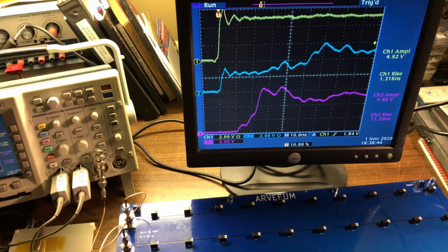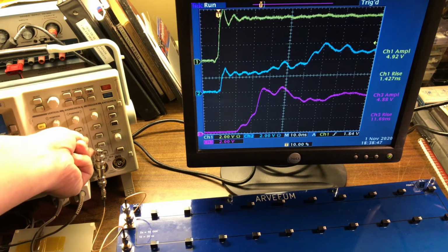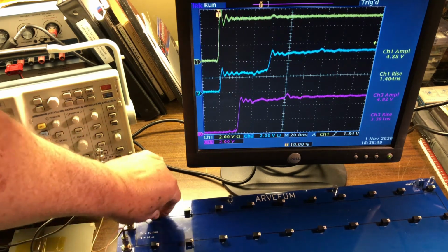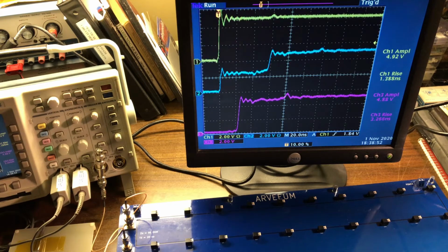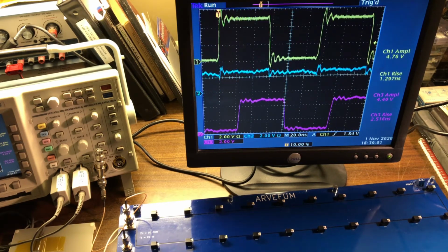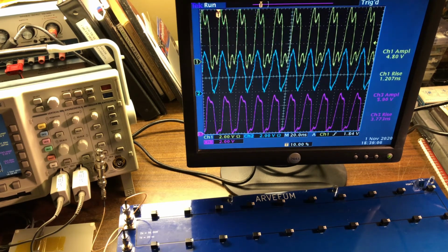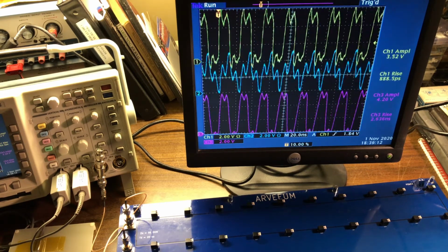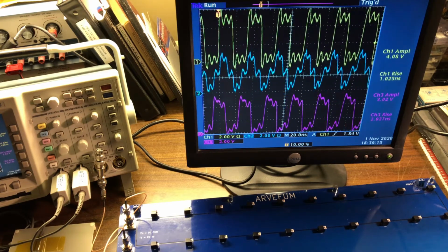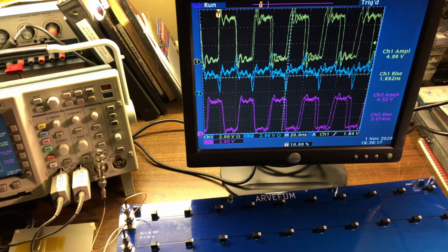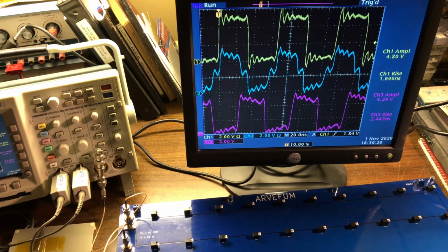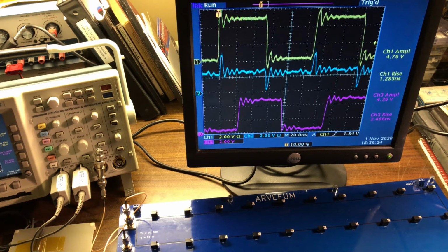Well, I'm at 1 megahertz right there, and I just want to show you what it looks like if it's nice. So all those transformations that the clock line have, and here you see that the shape does not change horrendously. The edges are there, and there is some change in the line. Then now we're back at 50, but there's not a lot of trouble with the line. There are some spots that are kind of weird, but for most the edges stay nice at around 2 nanoseconds,